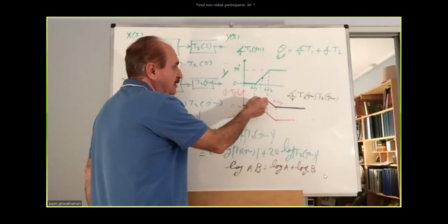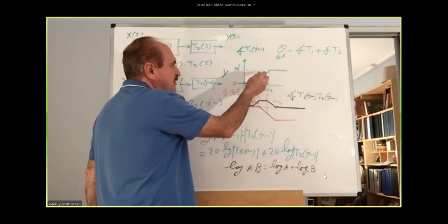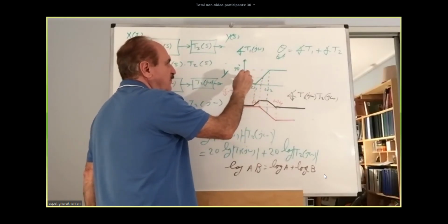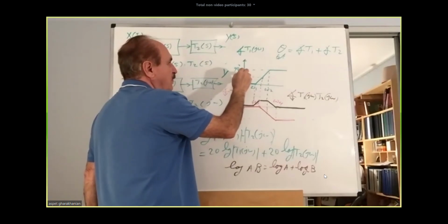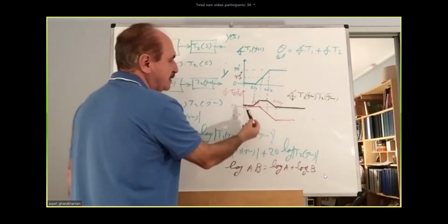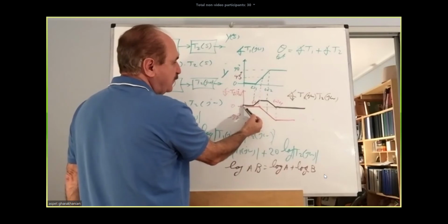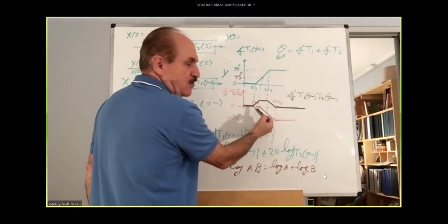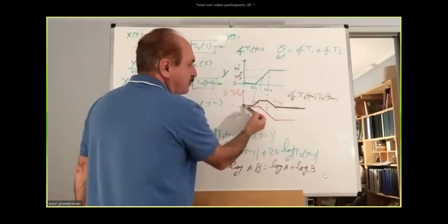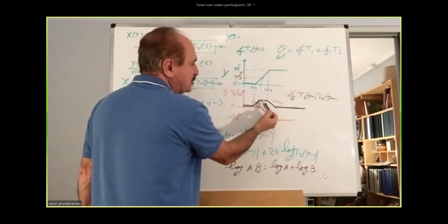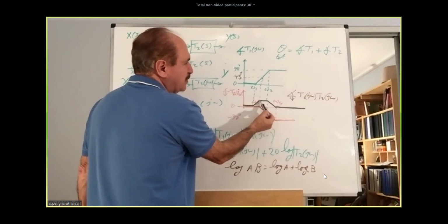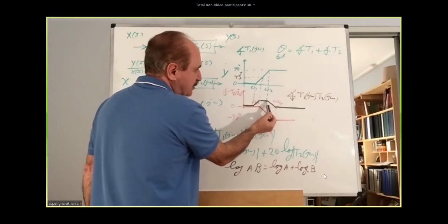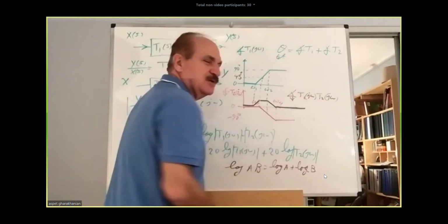Because the angle that it broke was in the middle, we can really call that 45 degrees. So we are estimating our phase angle is going to shift from 0, of course, much smoother than a straight line, slowly rising, peaking, but not exceeding about 45 degrees, and again going back to 0 degrees.